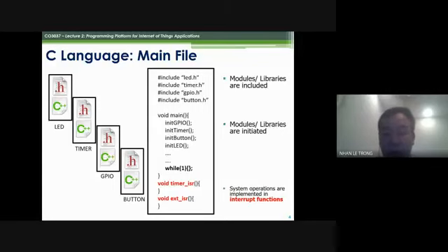But there is a little bit of delay for the timer interrupt service routine. But the behavior is almost the same. Whatever you have in the while true or in the timer interrupt service routine is going to be repeated forever, right? So while true and timer ISR are almost the same. You can implement it here or here. It's going to work.